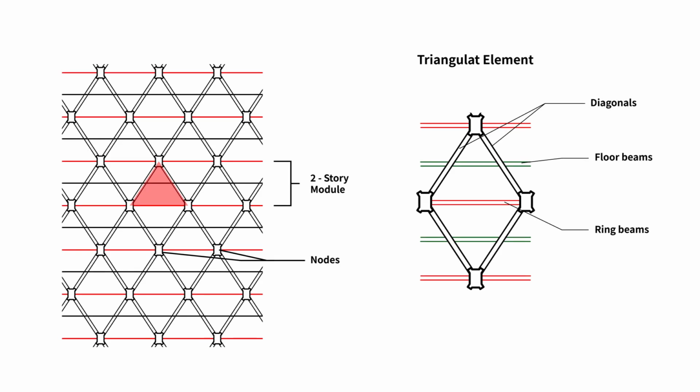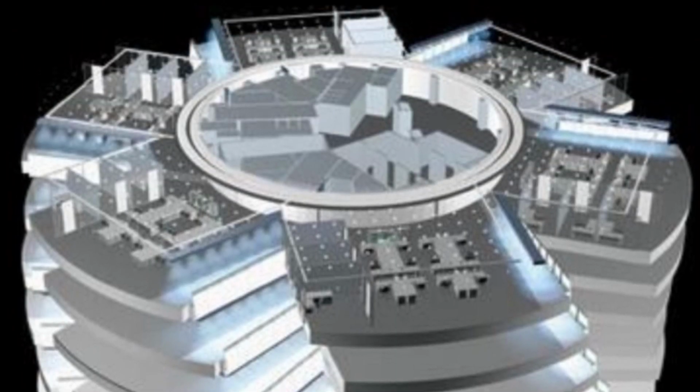The St. Mary Axe building's diagrid system used a triangular module designed based on the height of two floors. Each floor follows a plan that rotates by 5 degrees. This sets the angle of the two-story diagrid to a total of 10 degrees.